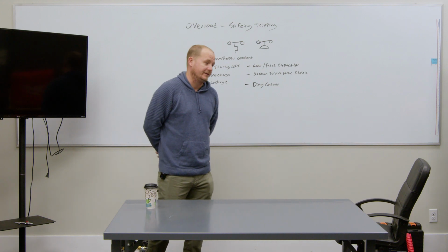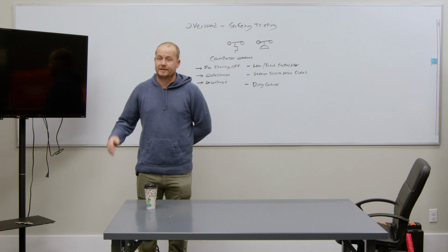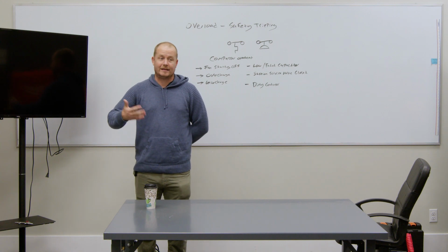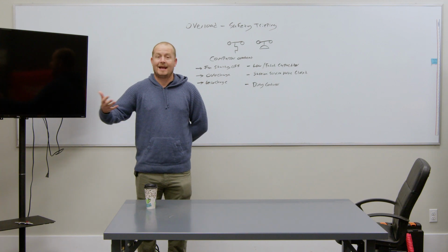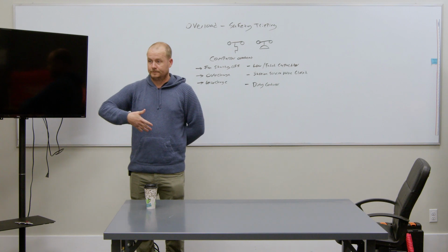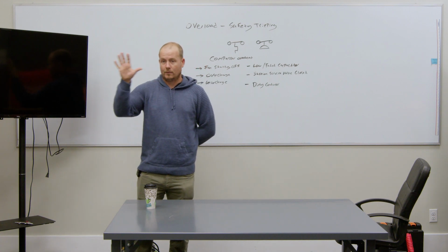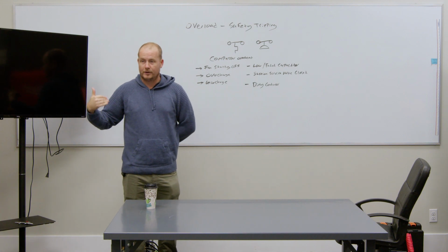And in a circumstance like the one we just talked about, condensing fan motor overheat, where the condensing fan motor runs a while, then eventually it gets hot enough that its thermal overload trips, then that takes out the high pressure switch or the compressor thermal overload. Are you kind of getting your head around what we're talking about here? So what I'm wanting you to think is a couple layers deep on these problems.